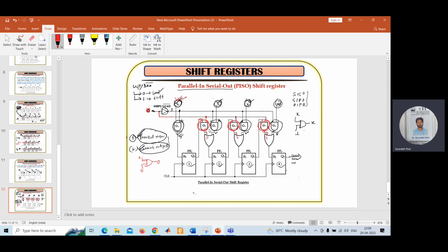So ultimately, it indicates that at that time, the input you have given in X1 comes only through this OR gate, because this G5 output is 0. It means that the output you are getting from G2 is the only thing you get from this OR gate. Similarly, the same thing is applicable for the second one also. What input you have given in X2, that is only what you get from the output of this gate.